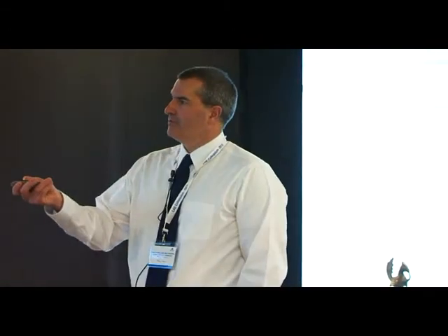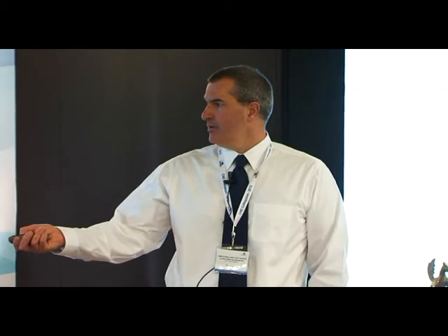For you guys who are interested in CFD out there, some details on the analysis tools that were used. It was CFX version 11, so this is a few years old, this study is. Second order spatial discretization, first order temporal discretization, and fairly standard modeling for the rest of the components. Two equation turbulence and fairly basic heat transfer modeling. This is a blowdown tunnel, so the test time was about 3 milliseconds or something like that. So really there's no change in the blade metal temperatures during this test.